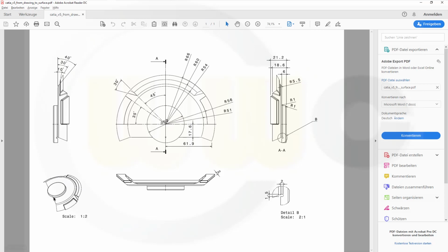First I want to do that cylindrical surface, then I will do this one with an extrude, then this one, the 40-degree angled surface with a ruled surface, then this will be a filleted pocket, a face-to-face filleted pocket. Then I want to cut out this here and add two more ruled surfaces and then close that gap. So that's the idea. Let's go back to our model.